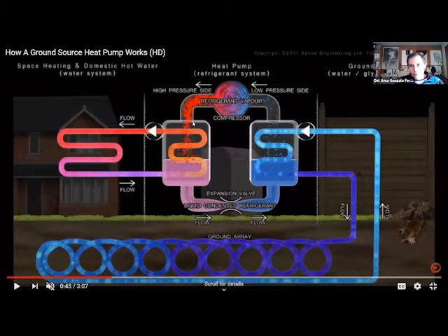We have to talk about the fluids here. In the loop inside the house, we have water. That's why we have water systems here. Outdoors, we have water plus glycol. This is to avoid freezing. So it's water, but we have something that prevents water from freezing. That's why we have this glycol. That's another fluid, but we can say that it's water as well.